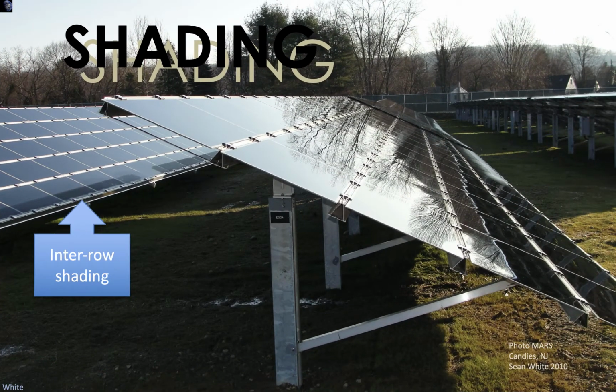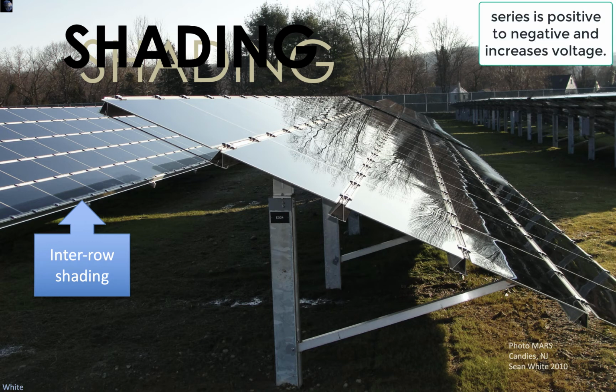Let's talk about shading. Shading is something that we try to avoid with solar systems, especially because we have solar cells at least, and a lot of times strings, that are connected together in series. With series connections, shading is not always proportional. That means that you could perhaps shade 10% of a module and lose all of that module's production. It depends on the module. It can get kind of advanced in the explanation, but let's do it.